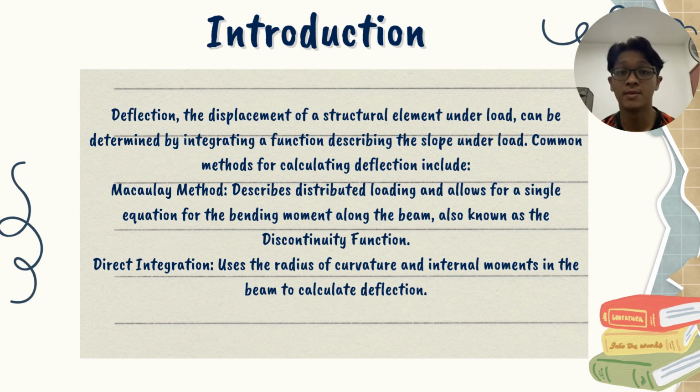Deflection, or the term that means the displacement of a structural element under load, can be determined by integrating a function describing the slope under load. A common method for calculating deflection is the Macaulay method, which describes the distributed loading and allows for a single equation for the bending moment along the beam, also known as the discontinuity function. The other method is direct integration, which uses the radius of curvature and internal moment in the beam to